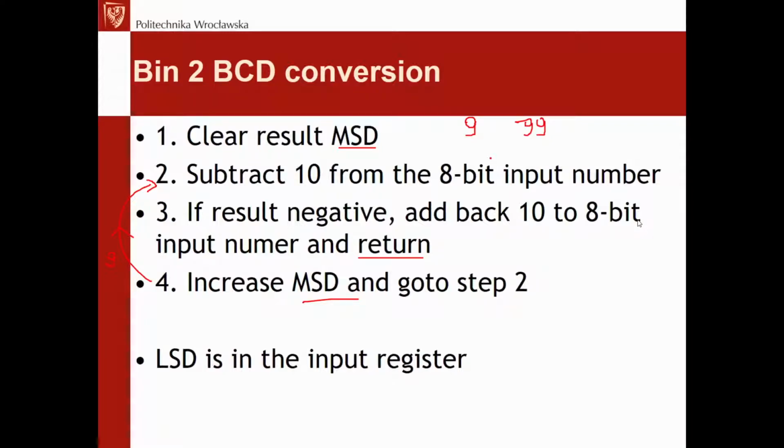So of course today, in the microcontrollers that we are working with, it's really worth first checking: would it not be better to use simple division? Because with division, we divide the original binary number by 10, and then we multiply it by 10. Because when we divide, we get rid of the remainder. And from the integer part, we multiply by 10, and we subtract the result.